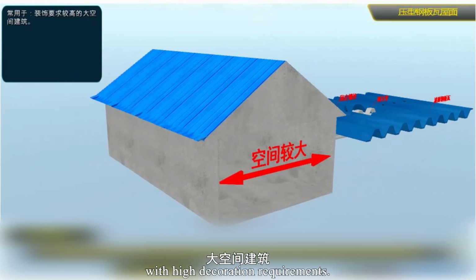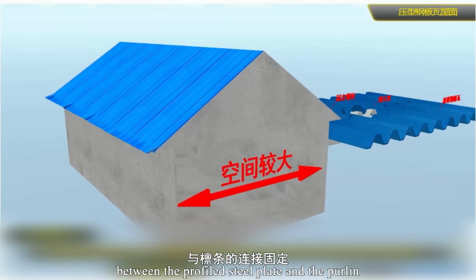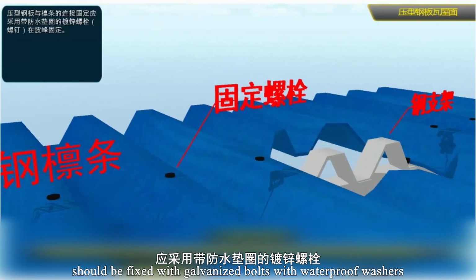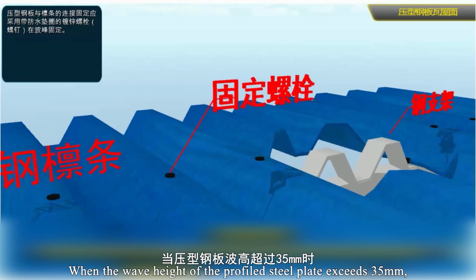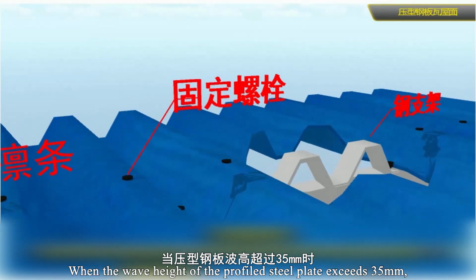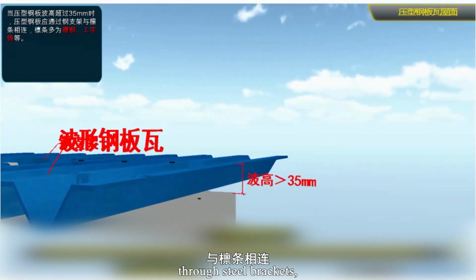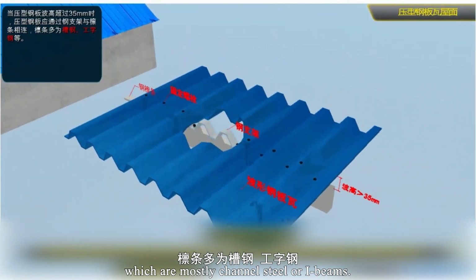with high decoration requirements. The connection and fixation between the profiled steel plate and the purlin should be fixed with galvanized bolts with waterproof washers at the wave crest. When the wave height of the profiled steel plate exceeds 35 mm, the profiled steel plate should be connected to the purlin through steel brackets, which are mostly channel steel or I-beams.